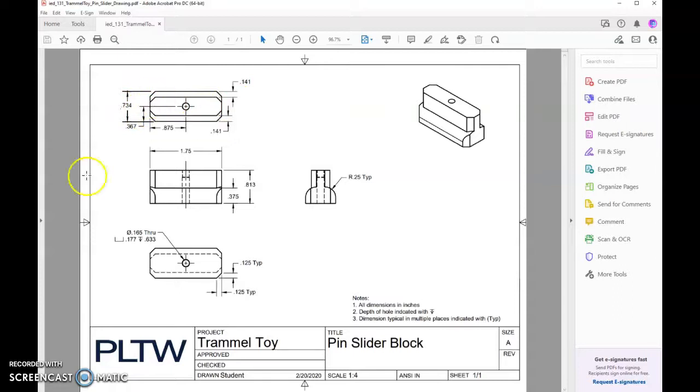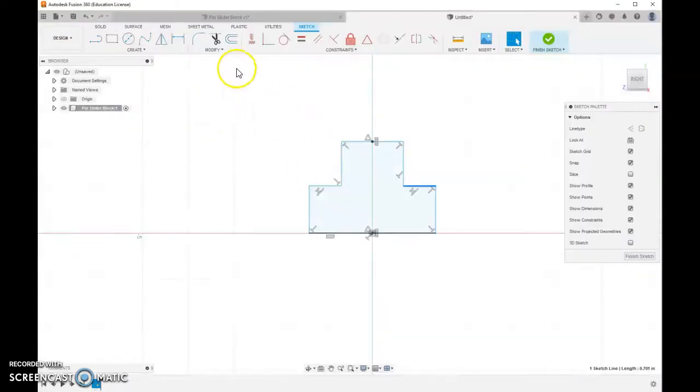So take those down. I'm going to go back into my drawing. Over here, you'll hit Sketch Dimensions. Let's just do a couple of things here. I mentioned that the height of the shoulder is 0.375. So I can go from here to here for a dimension, click out here, and then put 0.375. Now when I enter, this is going to make it look radically different because I don't even know what these dimensions are right now. If I hit 0.375, yep, it's really far off.